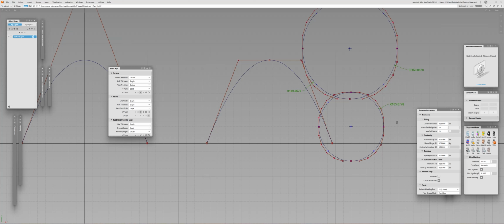It's already difficult to control, and that's why, if you really have a long curve with a lot of torsion and bend, these spans, which the vector knots basically define, let you divide it into chunks and process them separately. That gives you the ability to maintain this beautiful complex curve and at the same time limit the fluctuations within the span itself. So this is a limited ability of control.